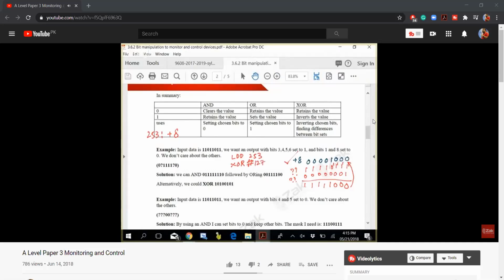So 127. If you like it to be in binary, then binary 1, 2, 3, 4, 5, 6, 7, 8. If you like it to be hexadecimal, then the and sign and FF. Got to remember all this. Whatever it is, all ones. This would give us this. Now you know how to do it. And this will be saved back to what? The accumulator.